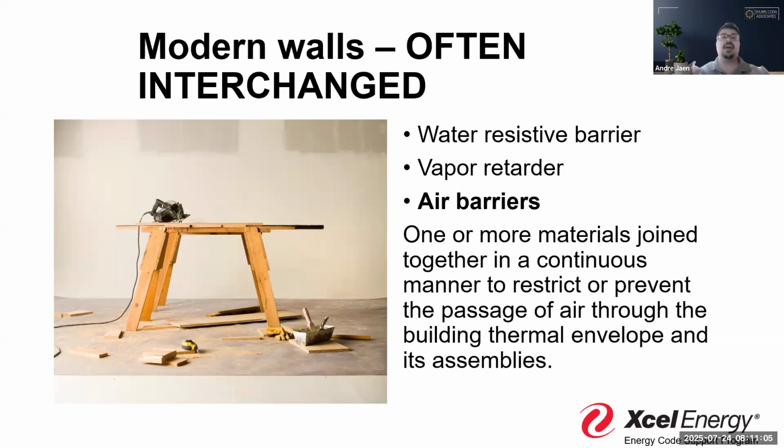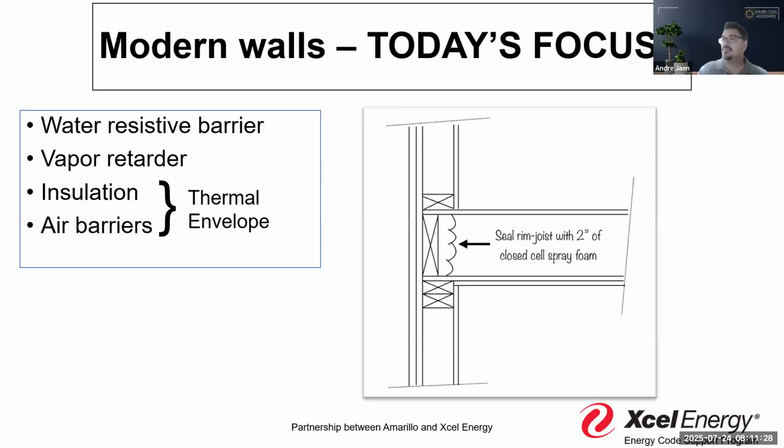So we're thinking about how this is going to join in holistically. And remember, the building thermal envelope is encapsulated on all sides. It's six-sided. It's every side of the building, right? That's full and complete. If we're leaking air in any place, then that diminishes our ability to say that we have a complete thermal envelope. And so this is really tied together at the hip with where insulation goes and where we define that exterior thermal envelope. So let's talk about some examples of these, right?